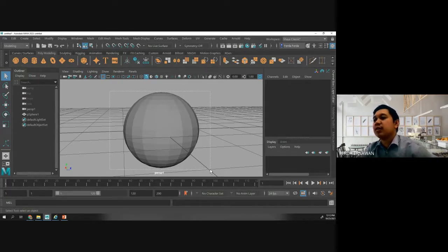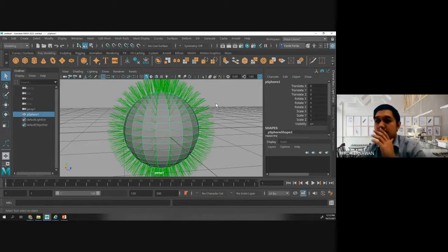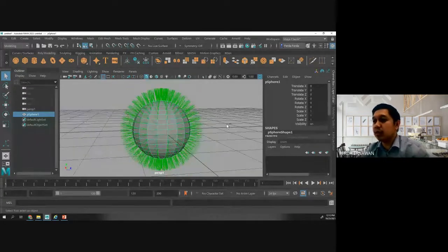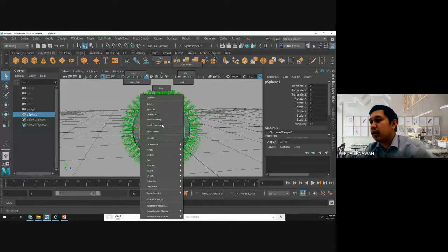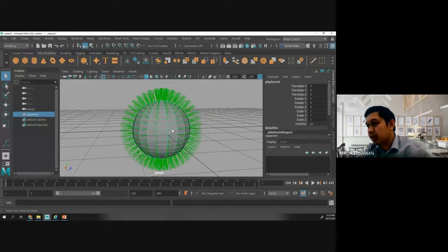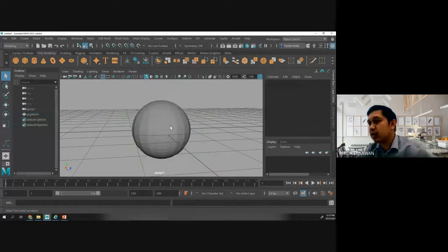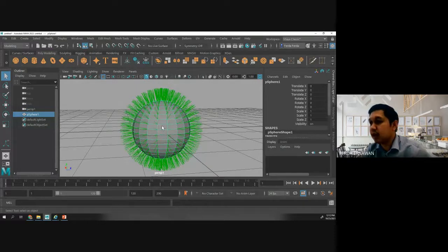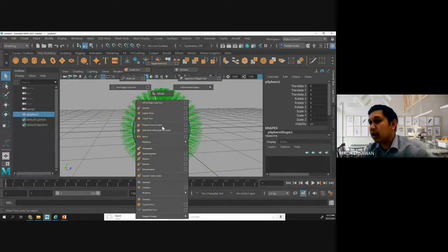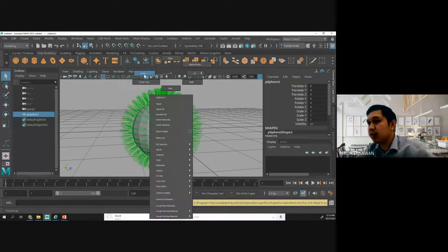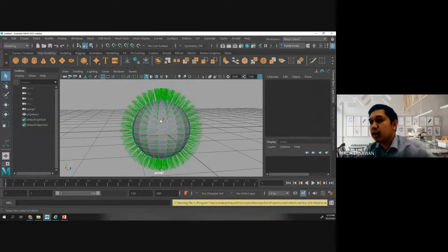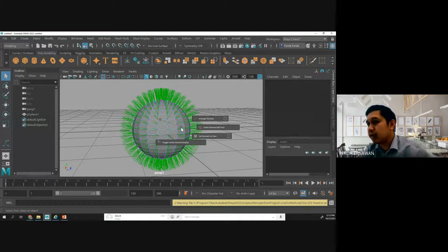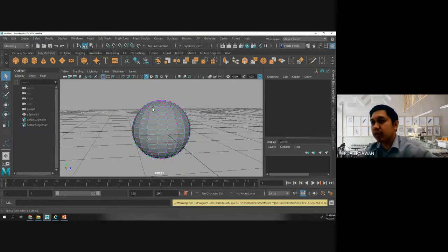So next, for example, we are going to create the 3D models here. Let's say I'm going to turn off the vertex here. I go to click here, Shift again, and then I have to go vertex first, like this. Then I go to vertex normal, and then choose the vertex normal display. So I remove everything.